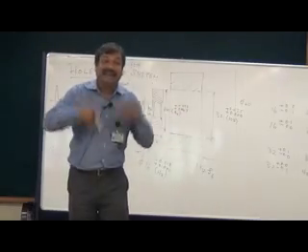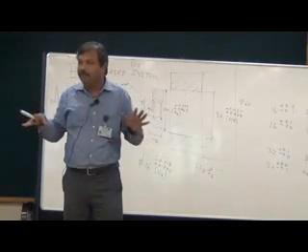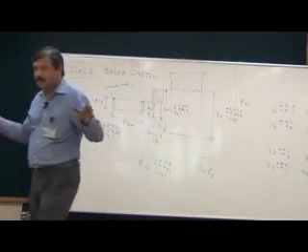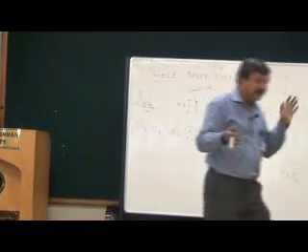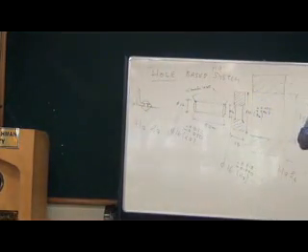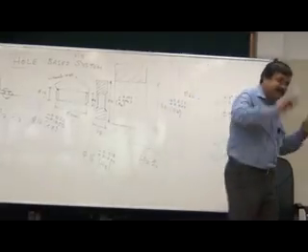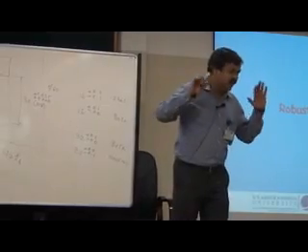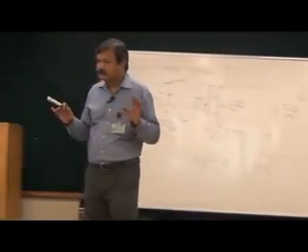Okay. Let us redesign the furnace in such a way that you provide fans, you control the flow of air inside the furnace so that the temperature distribution is more uniform. Got it? I have to redesign the entire furnace in such a way that there is a uniform temperature distribution within the furnace. Then the problem is completely solved. If the temperature distribution is uniform inside the furnace, there is no overburning or underburning of bricks, the problem is solved.